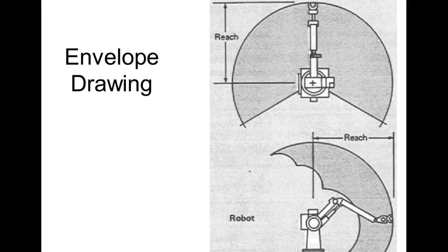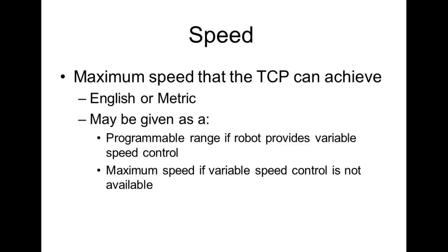And y'all had to develop one of these. This is what we were looking for when you had your gray robot. Not only did we draw what it does horizontally, we drew what it does vertically, and then we take this and place it on that, and that would be the actual envelope. Of course, we would take an infinite number of these and move it around, and you can see this forms a sphere, right? In a jointed spherical, though, the inside usually looks kind of like this, and that's the big difference between a jointed and a regular spherical robot.